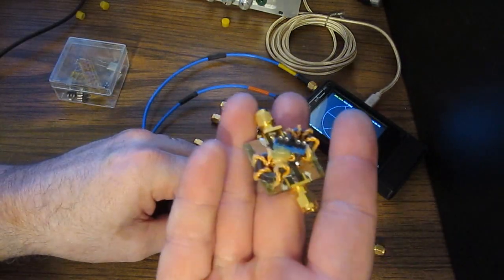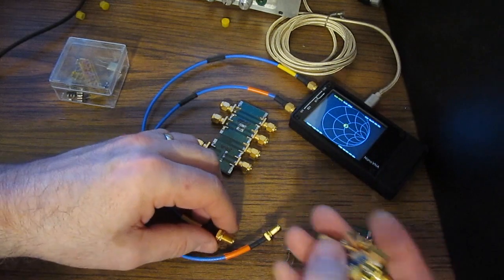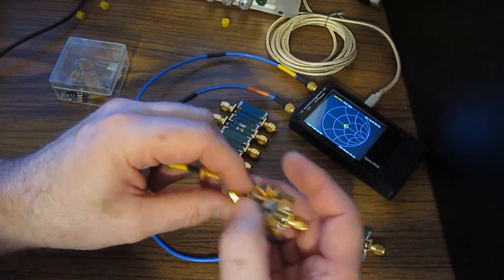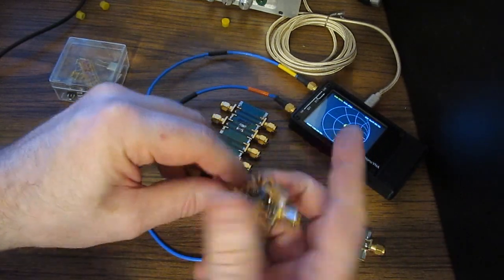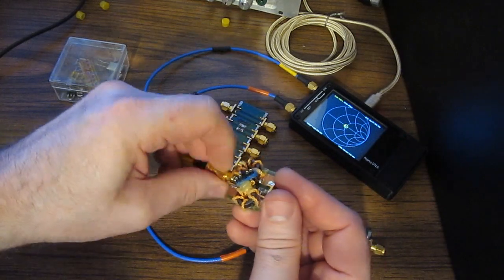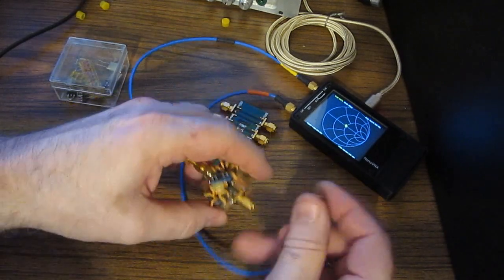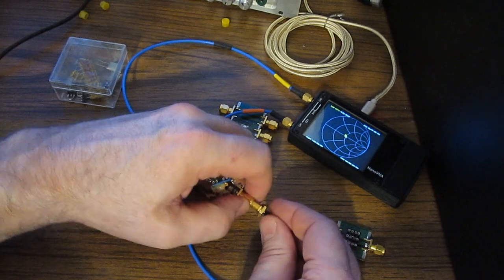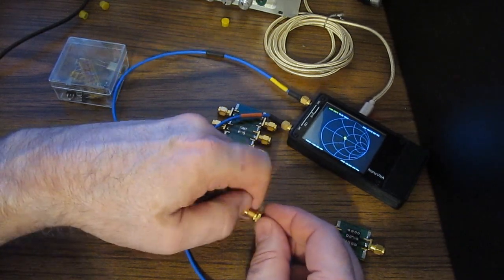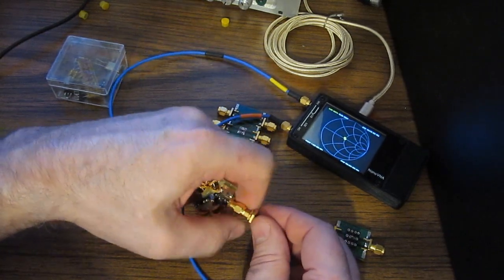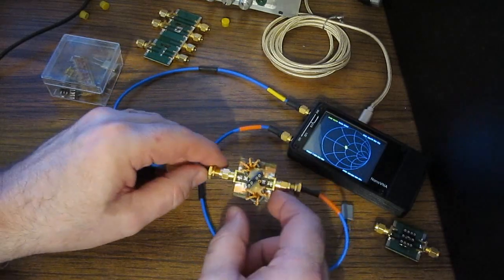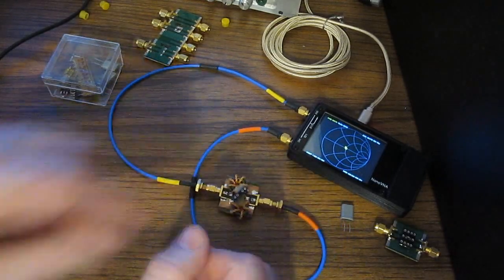Again, you're going to have to start out by building some sort of a test fixture. If you look in the manual for the software that I've written, I've documented this particular fixture. I would suggest that you build something like it. This one is good for taking measurements up to, I don't know, 25 megahertz crystals or so. You probably don't want to go much higher than that. Again, we just insert this fixture between port 1 and port 2.